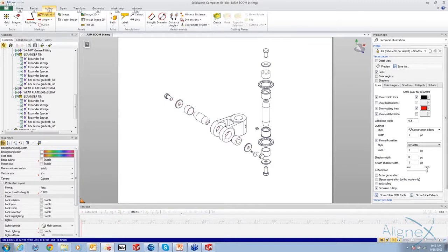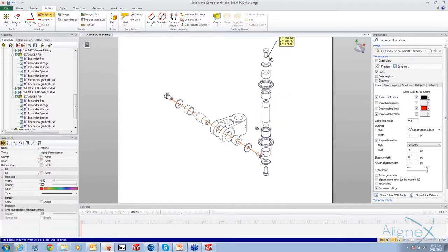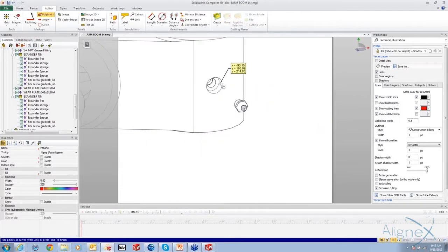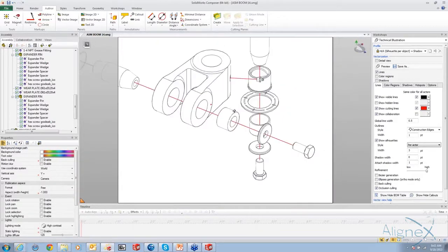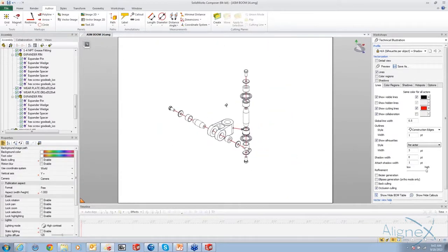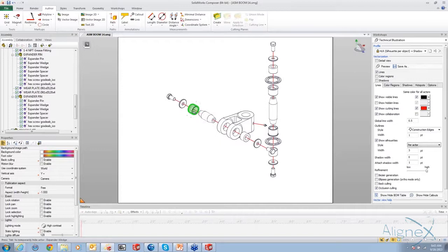And what I'm going to do is I'm just going to snap to these components so it's actually in the correct location there. We'll go from this component here. There we go. And then lastly, we want to show a line of this coming out as well. There we go. All right, so now we reposition everything. Now, the one thing about these polylines is we see that they're obviously not the right color. So we want to make changes to that.